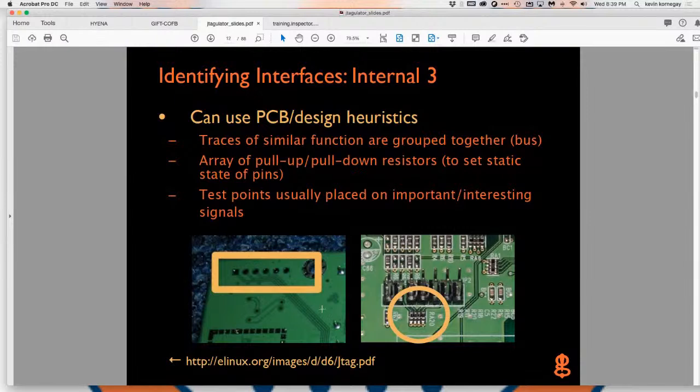So you can trace this back to the chip. You can follow these traces on the board, and then you can use a continuity test. You can set your digital voltmeter, your DVM, to perform a continuity test, and when you get the right tone, you know you can locate the actual trace all the way back on the board.